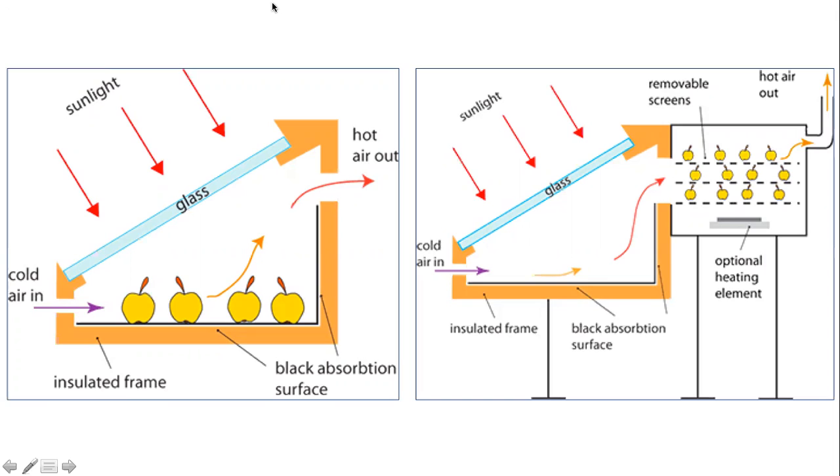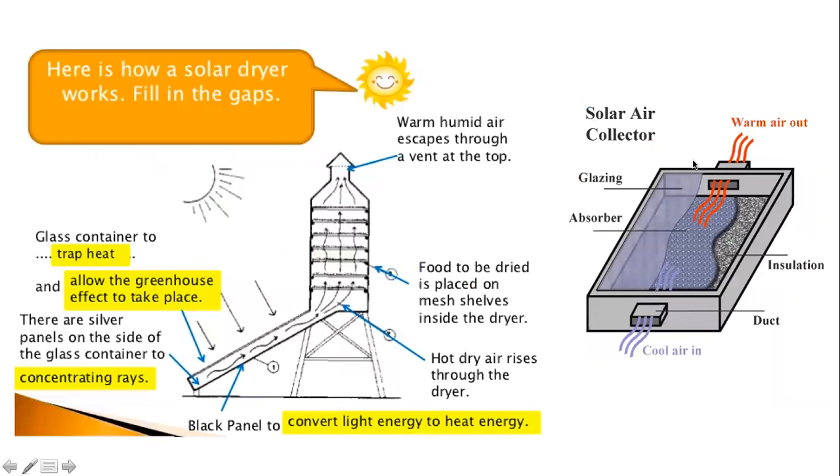So here you can see some disadvantages, right? Then contamination is there, not now, but in solar drying, contamination is there. And how to avoid this, how to increase the volume, then you can use such a modern device. Then you can implement some sensors with this device to control the temperature, right? Then how to get more energy? You can change the shape of this absorber, and you can change the material. And this is my example, this is my suggestion.